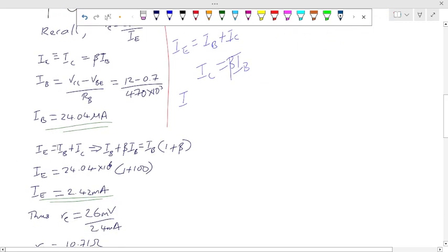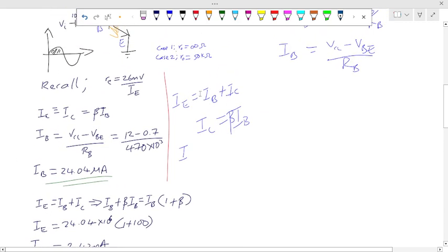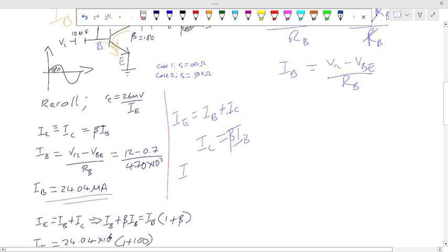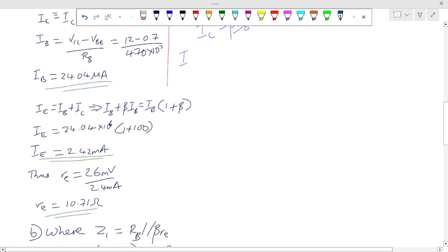Good. Now, back to this expression I gave earlier. We just substitute in this guy into this part where you see IC, put beta IB. Hope you are following. Please follow. You can pause the video, take it back, things like that. Here you see IC, put beta IB. Then you just factor out IB, you have this. IB, we've already solved it as this. You plug it there. Plug 1 is 1 now. Beta is 100 in the equation. Then you do your arithmetic and you arrive at this. So this is IE.